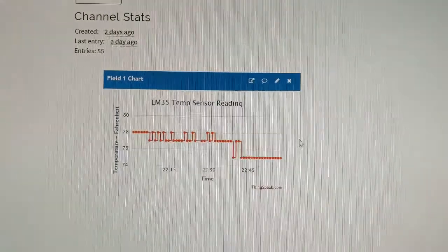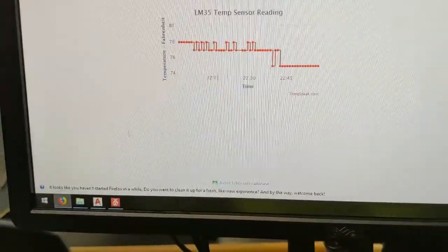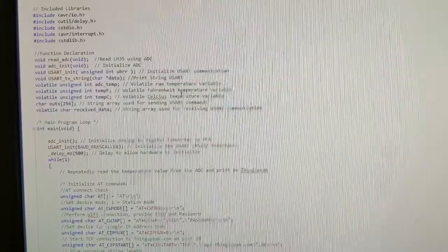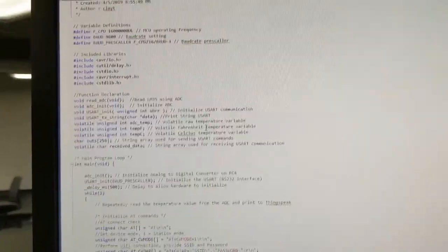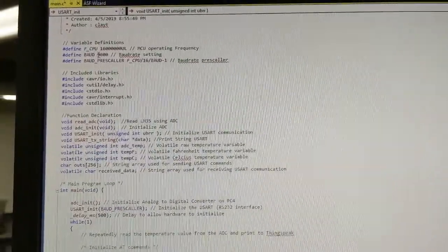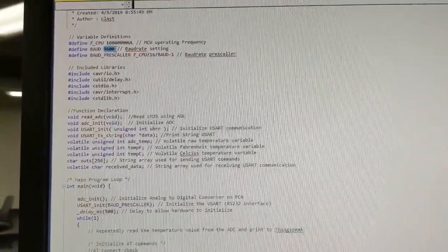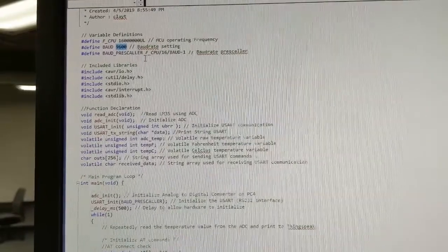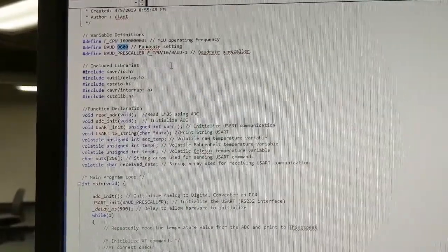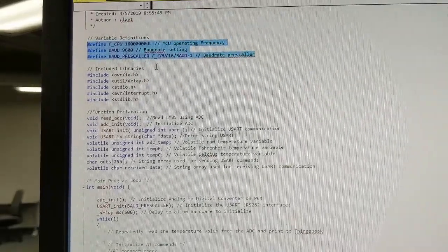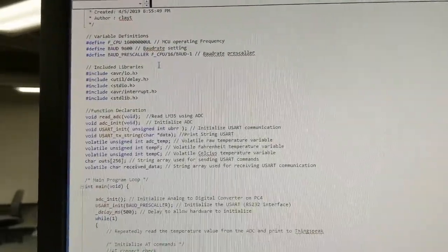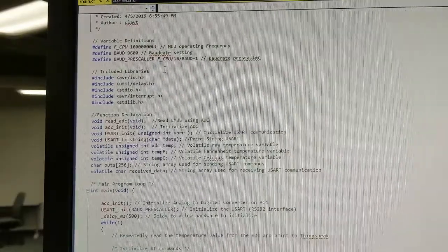It's been interesting. The one thing I was going to bring up is that we ended up figuring out that a lot of students tried to connect the device at 115200, the typical baud rate setting for the ESP-01 module, and had a really hard time getting it to communicate with the ATmega board.